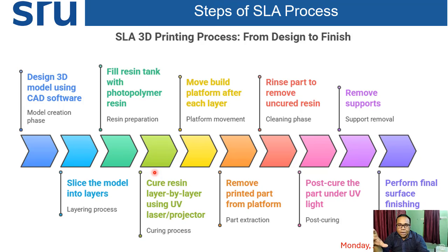Once the part is printed, you have to take the part, or semi-cured part, from the build platform, and then it has to be cleaned properly. After removal of the part from the build platform, you have to rinse the part with uncured resin, so that proper cleaning takes place. Only after that, the cleaned part will be sent to the UV light so that curing takes place. During the curing process, as we have discussed earlier also, the part will gain proper strength and hardness.